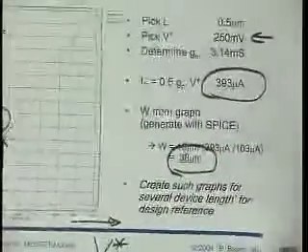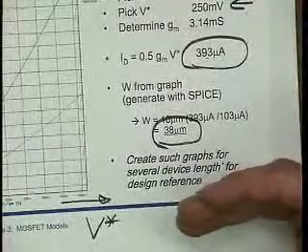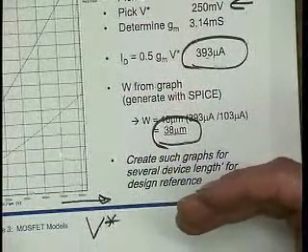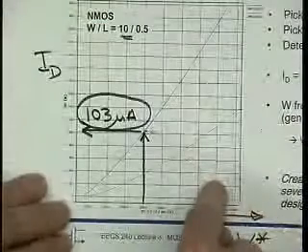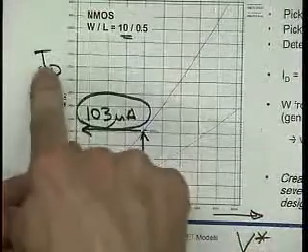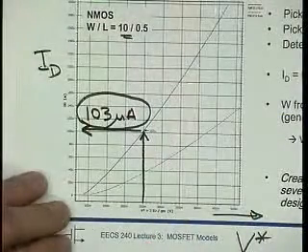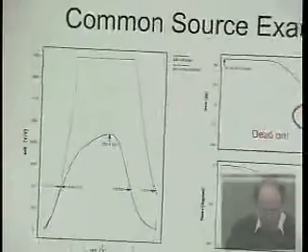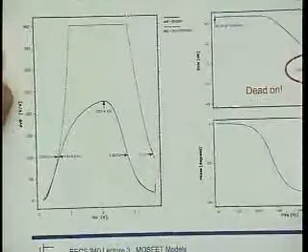Okay, so the most important stuff, of course, is these device parameters that we came up with, and then to make it work, we will need such graphs that relate V star to ID for a given W over L, and then we just scale the W, right? Okay. Very simple, and that's all you got to do for the homework. So the homework is really super simple. And you don't need additional stuff that the fab wouldn't give us.